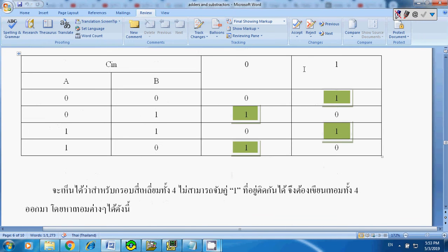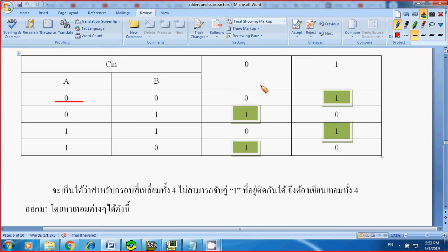Now the next step is how to minimize that term, because you want to write your output in terms of your inputs. In this case, it is 3. Okay, the way to do that is to draw a rectangle across the output logic 1 only.